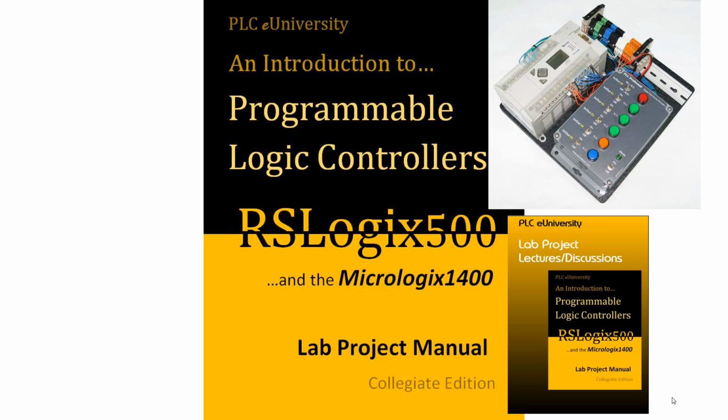Then we have this one, it's very similar, but it's not exhaustive in the instructions. There's much more programming and understanding of different styles of programming, but it was accomplished with a MicroLogix 1400. Now, the manual that you just saw, or this one, can be used with any SLC 500 or any MicroLogix. The only thing that you have to be aware of is the I/O assignments might look slightly different, but everything else is going to be identical.